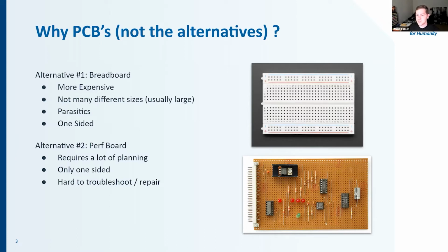It might be a little bit hard to see in this image, but can you see the little ICs, the little chips, how they're actually sitting on something? It's like a little package. Let me see if I can get a better example here. They sit on these sockets because if you need to pull one of these ICs out of a perf board and you don't have it sitting in a socket, you are probably going to rip the pins right out of it.